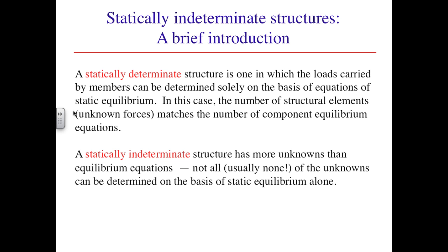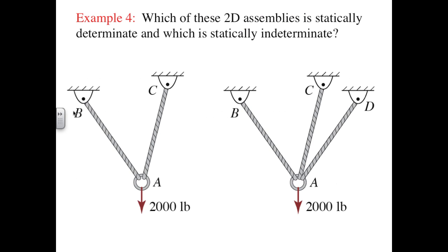In this case, the number of structural elements, that is, the number of unknown forces, matches the number of component equilibrium equations. In contrast, a statically indeterminate structure has more unknowns than equilibrium equations, and usually none of the unknowns can be determined on the basis of static equilibrium alone.